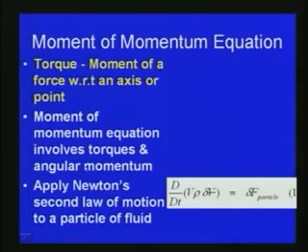In the moment of momentum, what we are considering is what kind of torques are developing with respect to the fluid system, and how the angular momentum develops. That is what we are going to discuss in today's lecture. To develop the moment of momentum equations we will again be using Newton's second law of motion applied to a particular particle of a fluid.